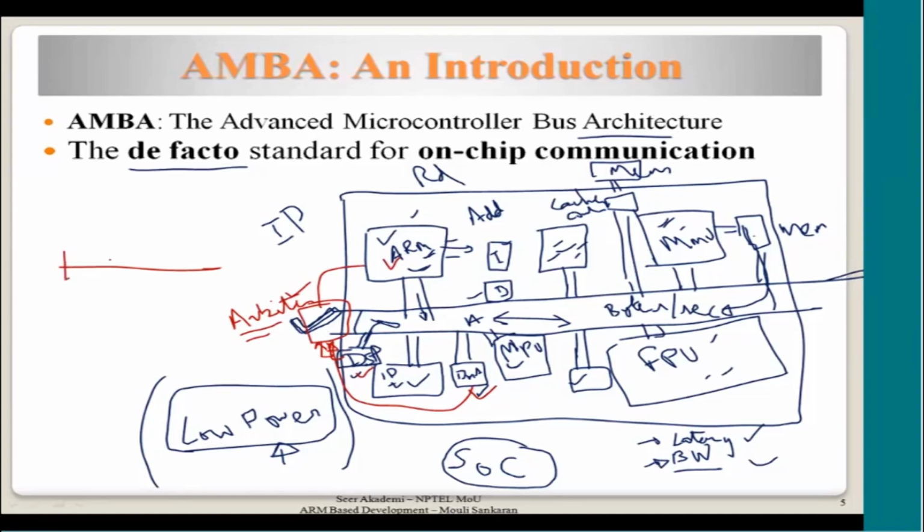So what I am saying is maybe from time t0 to t1, ARM can transfer over the bus, and then from t1 to t2, maybe the DSP processor on the bus can transact over the bus, and later maybe a DMA transfer could happen. So who decides who is the master at a particular time?